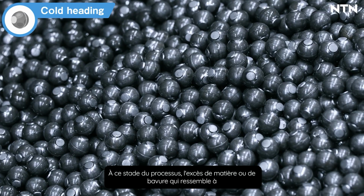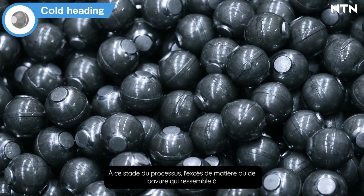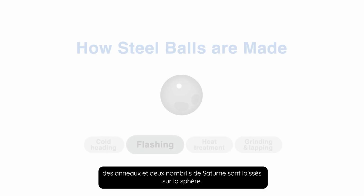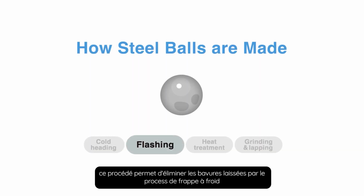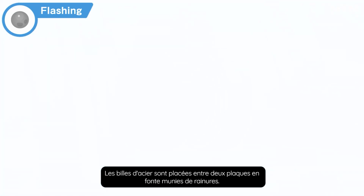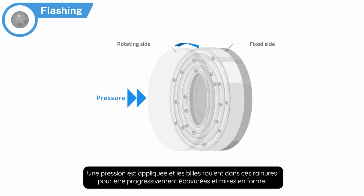At this stage of the cold heading process, excess material, or flash, that looks like Saturn's rings and two navels is left on the steel balls. Next is flashing. Here, the flash left from the cold heading process is removed. Steel balls are placed between two cast iron plates with grooves. Pressure is applied and the balls are ground while being rolled.